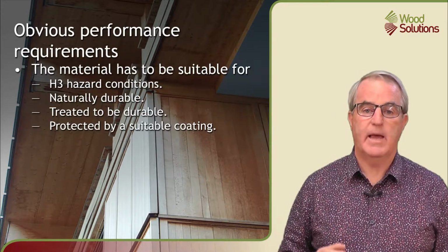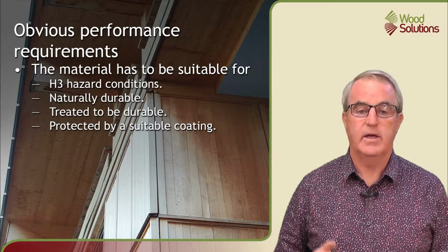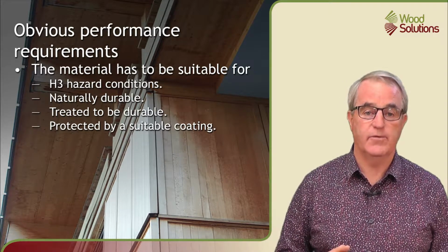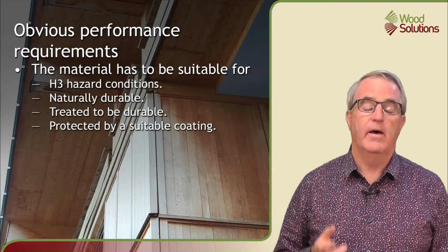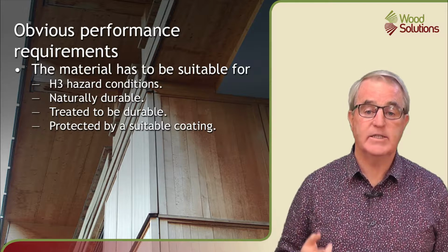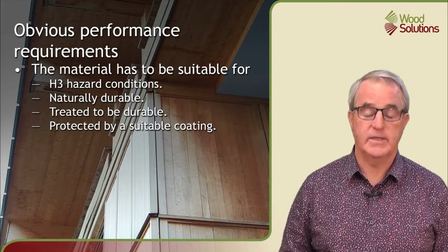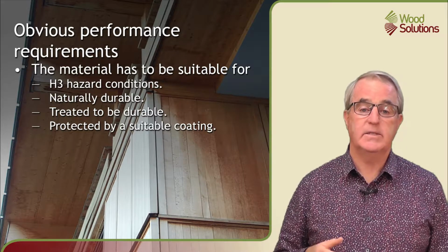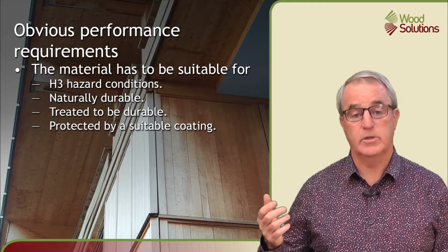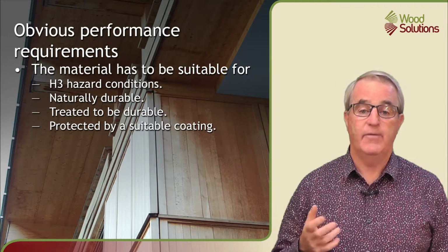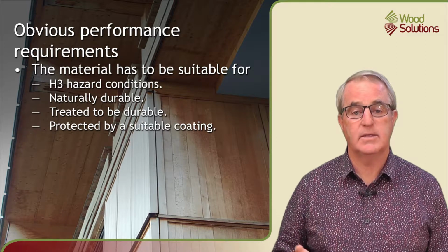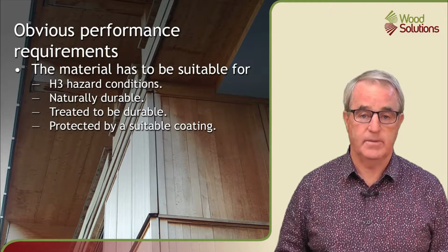Having determined that this is an application outside above ground, some key performance requirements are clear while others have to be confirmed through further questions. The performance requirements that are obvious include that the material has to be suitable for H3 hazard conditions. This means it has to be naturally durable, sufficient to perform satisfactorily for the expected service life, and effectively resist the effects of water, wind, sun, fungus, insects, and sources of abrasion.